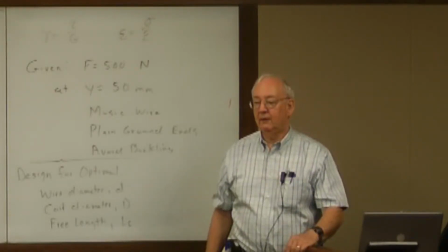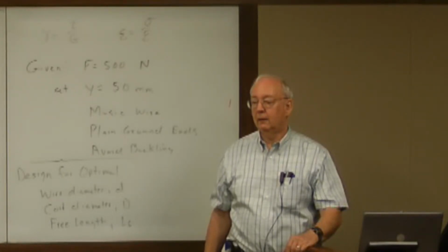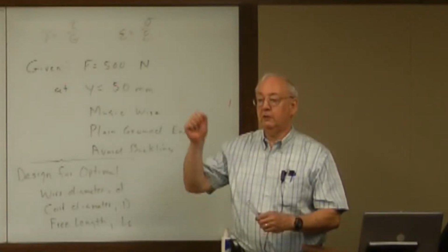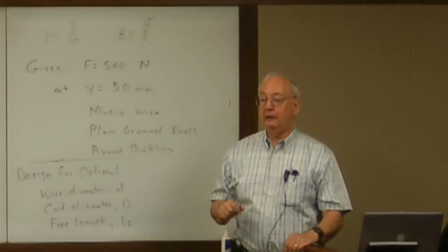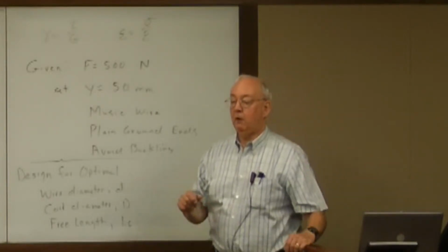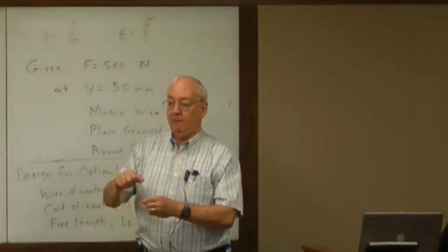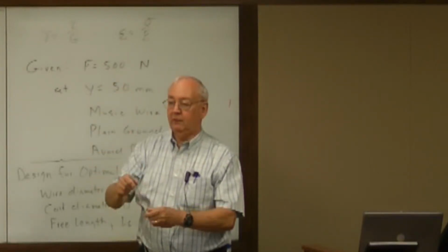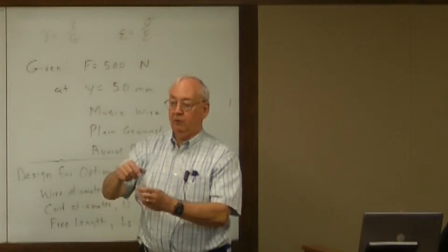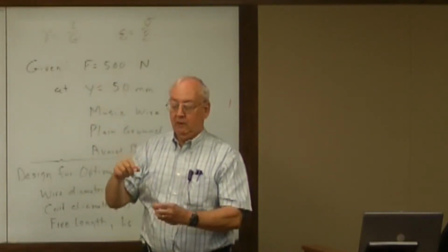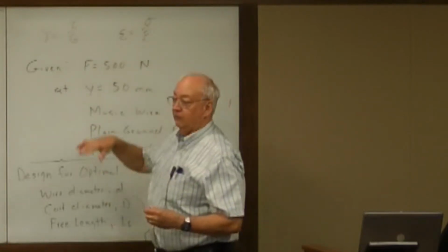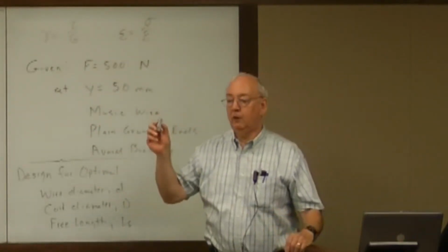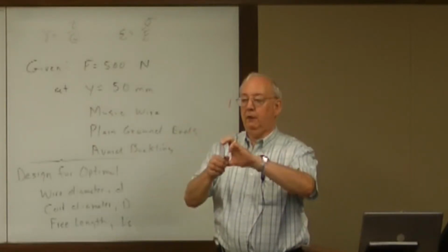If deflection is this, pushing down, what is this? That's deflection as well. Is there positive, negative deflection? Yeah, but that's another kind of spring. We have a spring called an extension spring. To obviously go this way, you need end hooks. And when you put end hooks on so that you can pull them, you get bending stress, this and this. So it's a little bit more complicated. One of the reasons I stuck with a compression spring, but that is another kind of spring.